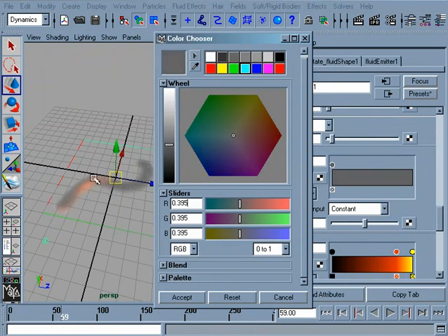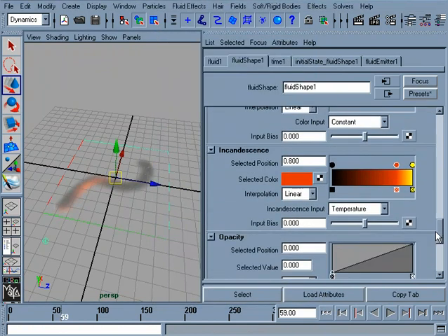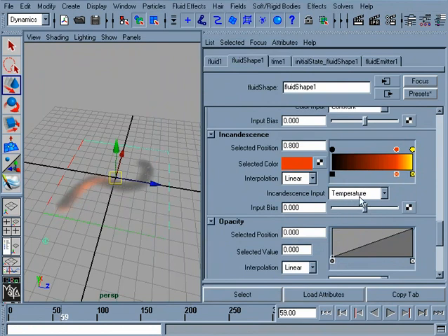Okay, now once this is set to a dark gray, immediately we can see that something has changed. Now we can actually see some of the incandescence that's being controlled by the temperature itself. So now we're actually seeing temperature as this is happening. So let me rewind this and play it through. And if we look closely, you can see that there was a little bit of a burst of fire in this area, so it got really hot, but then it just cooled off. And now this heat's just sort of spreading in a pretty nonsensical fashion. Just kind of chaotic at this point. So what we need to do is set it up to where this fluid can actually burn along this entire length.